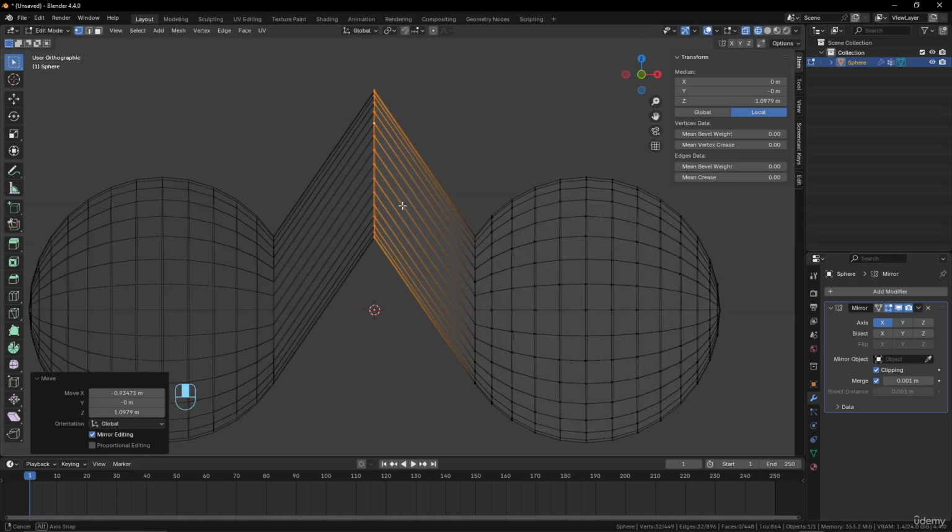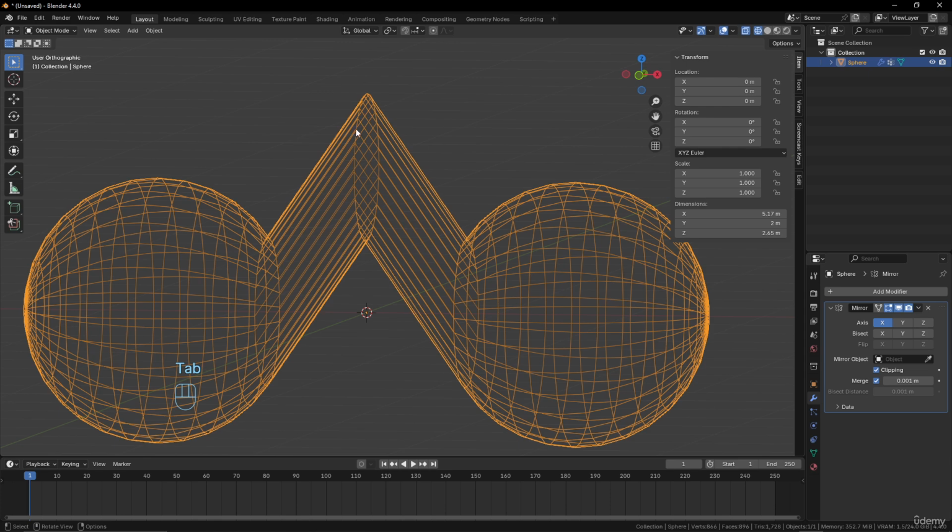And with the merge option here, I will export only one loop here and not two loops. If I don't use the merge, you can see the number of vertices that will increase here. So now I have 866, and if I remove the merge, it will increase by 32 vertices more. So yeah, this is the behavior that is important. Except that, it's a very powerful and useful one. We will use it a lot during the training as well.